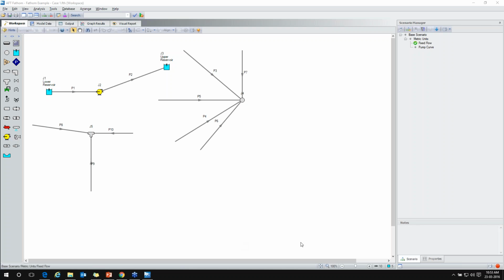Then there is another question: temperature rise of fluid in case of closure of valve outlet, pump discharge. Okay, yes, this can be handled. For this, we need to model the heat transfer case. If there is any mechanical energy that is converted into heat and transferred to the liquid, up to some extent, yes, we can model it. But to model these cases, we need to develop a heat transfer model. This can be seen under examples. There are various files available which handle the heat transfer cases for the pumps.